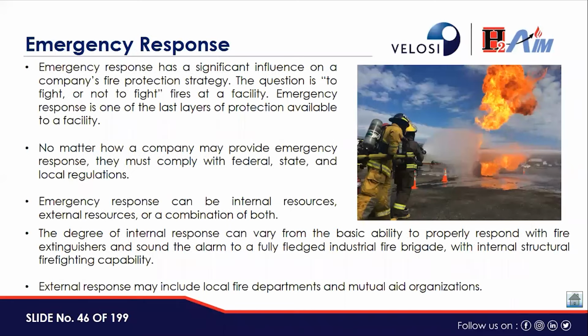Then, how can we mitigate the escalation of fire with the help of emergency response? Emergency response has a significant influence on the company's fire protection strategy. The question arises: to fight or not to fight fires at the facility. Emergency response is one of the last layers of protection available to the facility.